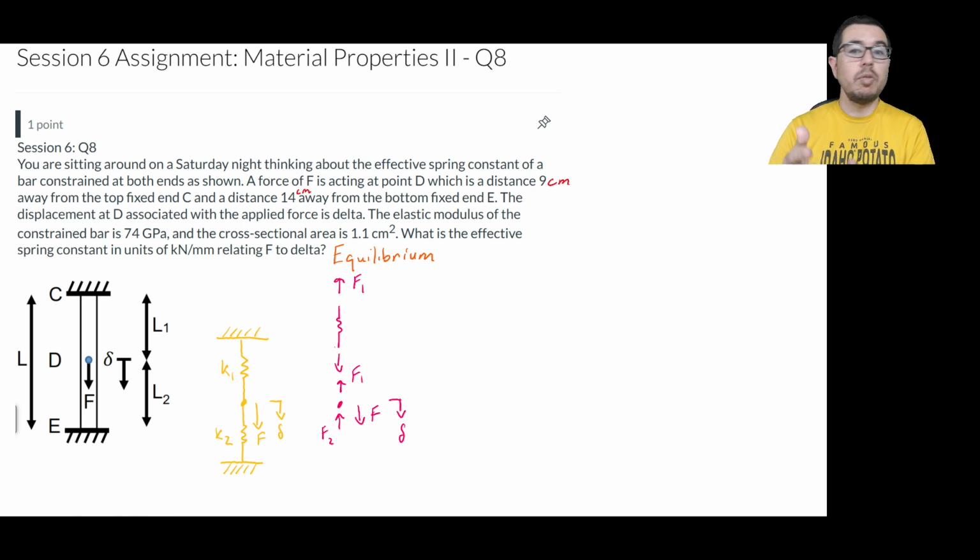When the force is coming out of the node, if it's positive, then it's going to have a tensile effect on the adjacent member. So we see that same behavior here. And this idea that we have tension in this spring also means that this wall up here would be applying the force upward.